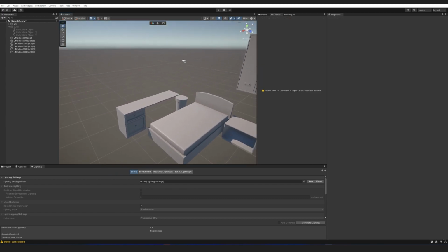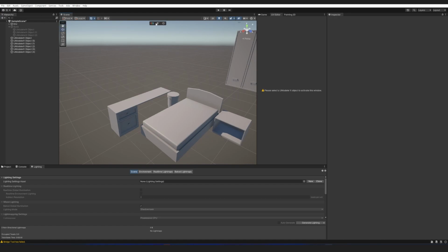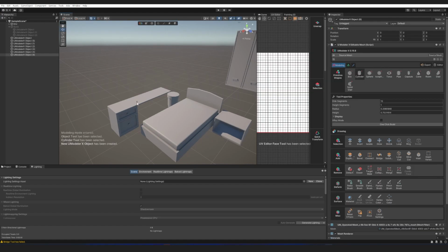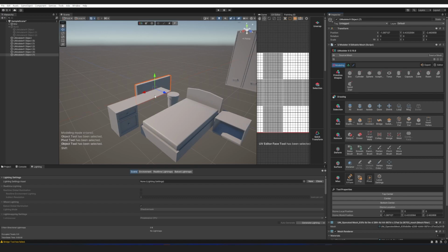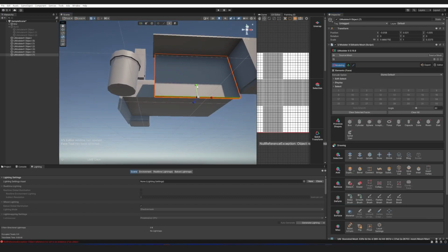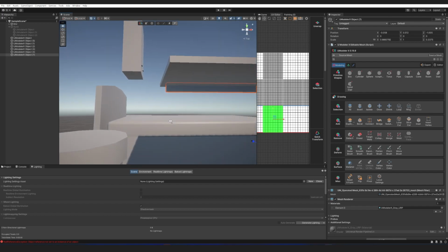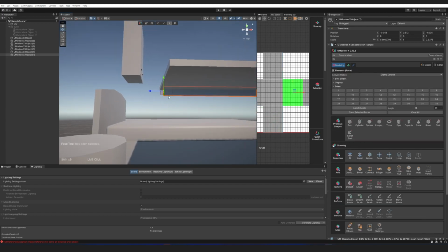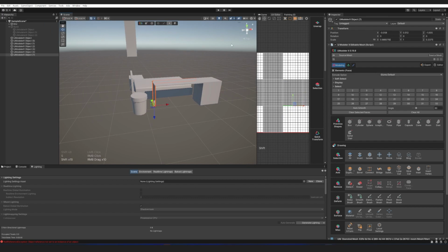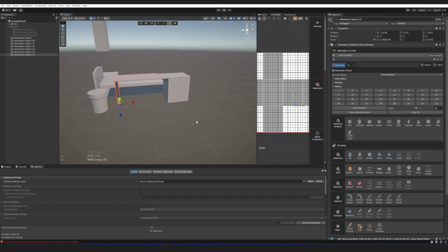Next, let's create the legs of the desk. Create a new object to make the legs for the desk. Adjust the size of the legs to match the proportions of the desk and create square-shaped legs. Use Extrude to create a face at the left end and extrude it downward to create square-shaped legs.